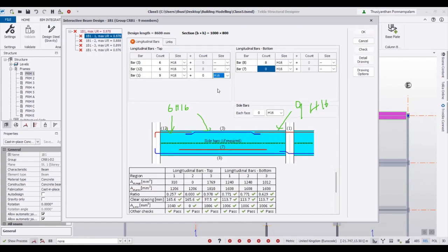Okay, I'm going to do this way. You see this 16, 16, right? So if this beam is less than 12 meter, we can provide one rebar throughout, right? We don't need to cut here and so on. So what we can do is provide the 6 bars here, then we can provide another layer here. It's all our detailing, or you can provide the 9 bars here, right? It's up to you to decide. Let's say you decide all 6 bars going through, just 3 bars below, you can do it. That's why I just want to show you, that's all. But you don't need to follow exactly the same.